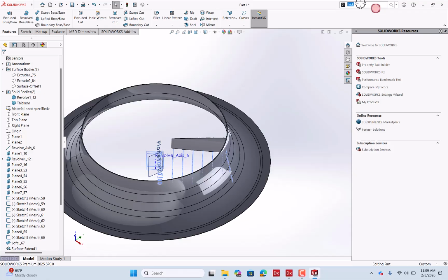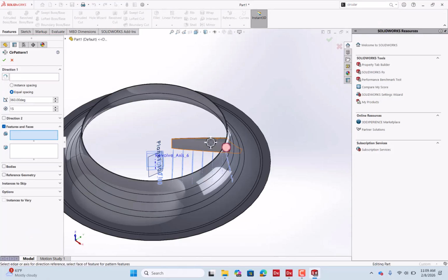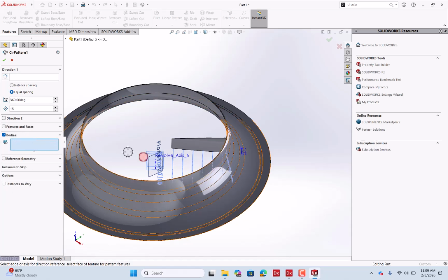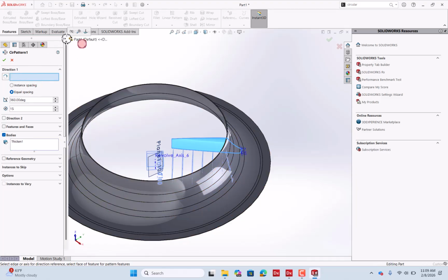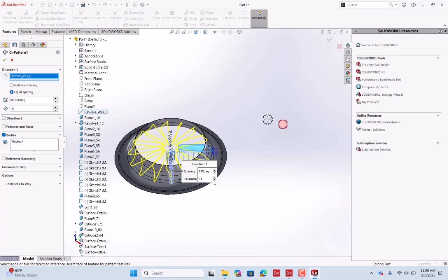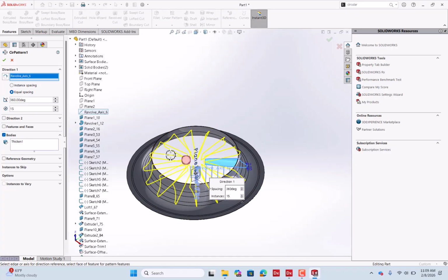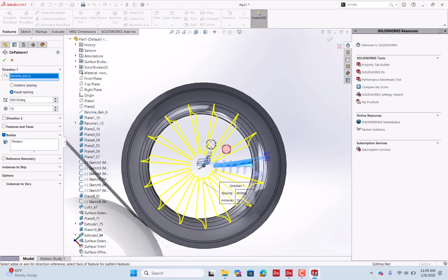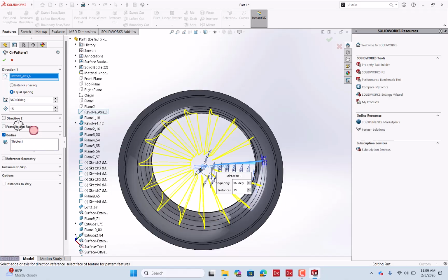This can then be used with a circular pattern tool. So here you can pattern this body. Instead of faces, you can choose bodies here. Then you can choose the direction, which would be your vector 1. So I can choose the revolve axis, and I can choose how many bodies need to be revolved. I can enter the number 15 here and say OK.